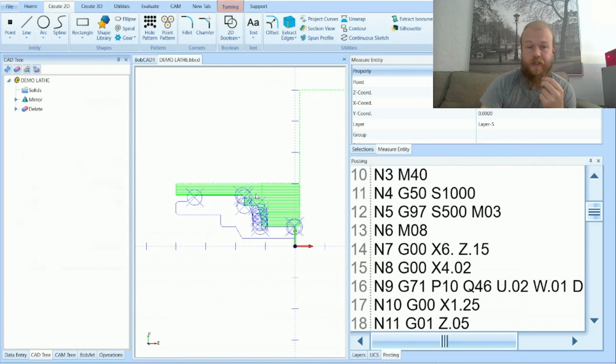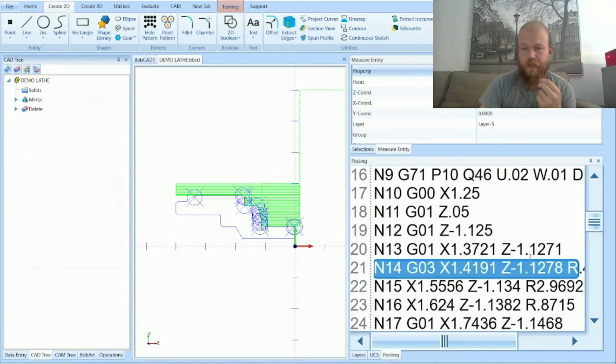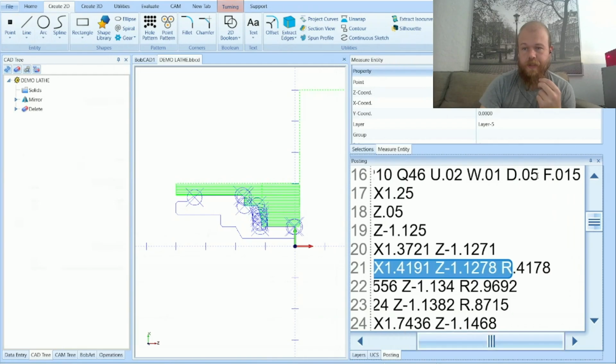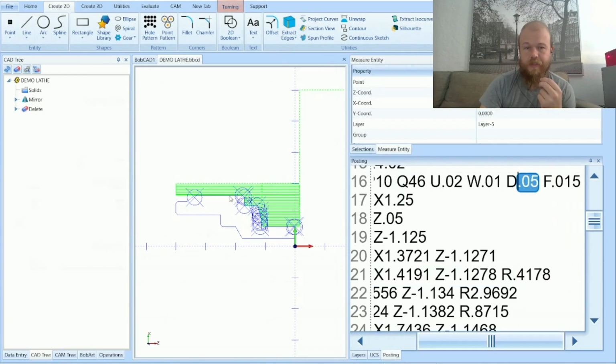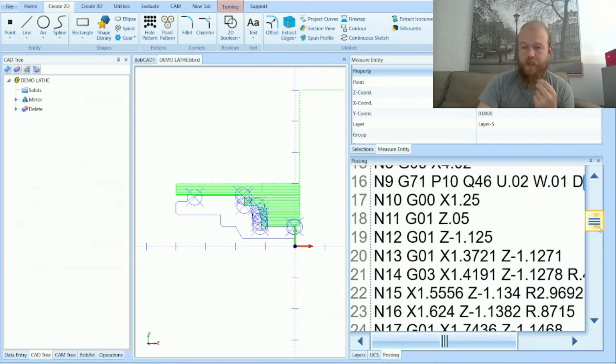the machine, it's telling it, okay, this is the profile from the stock that you have. Just do a depth of cut of 50 thou every time until you get to this profile that we created from point to point here. And so it shortens up the G code by a lot.